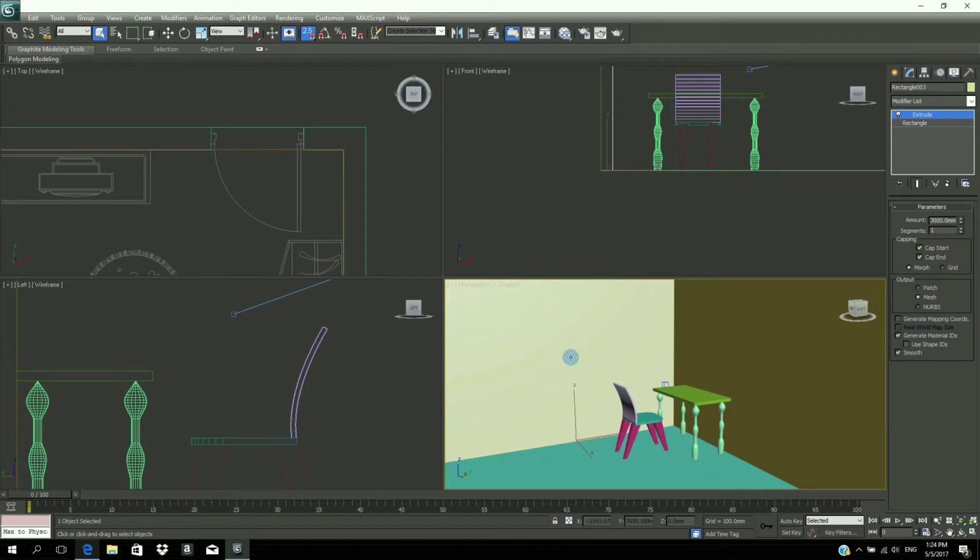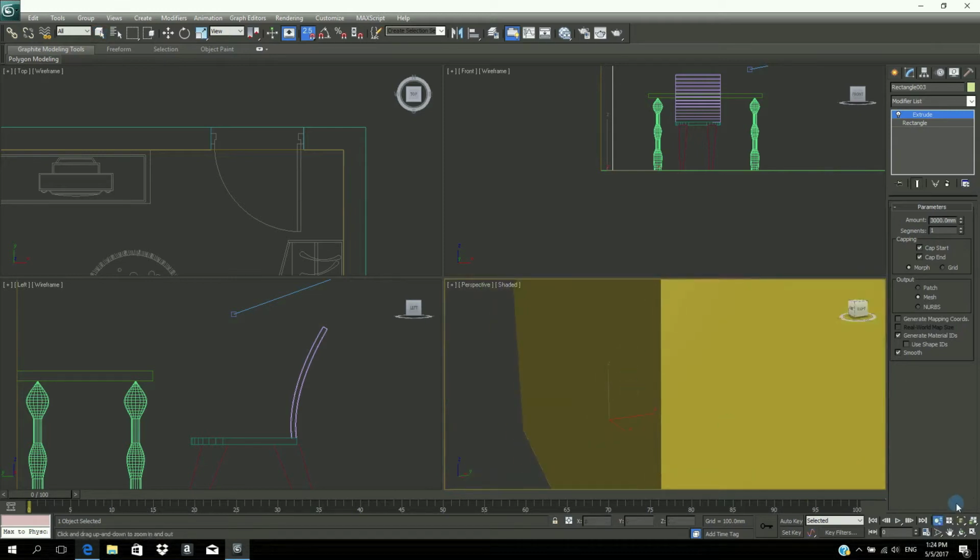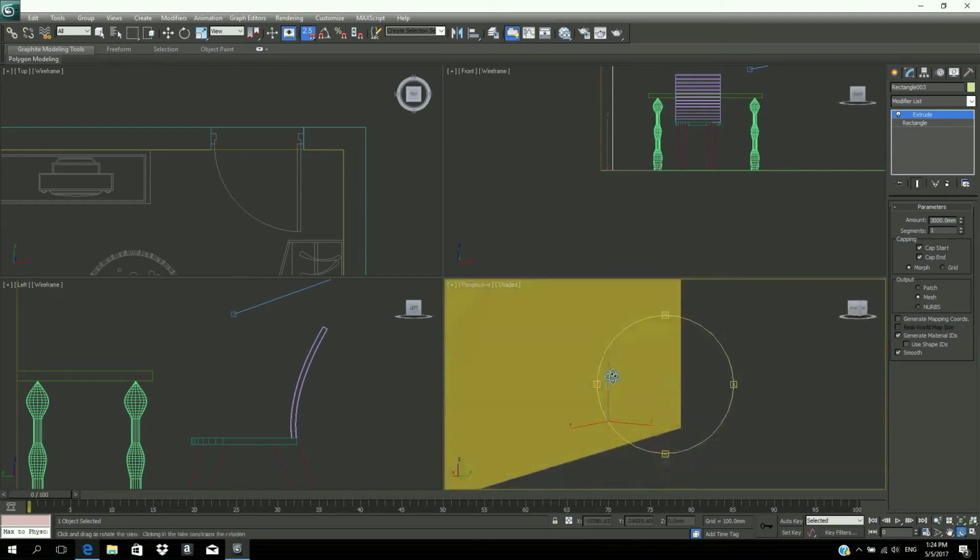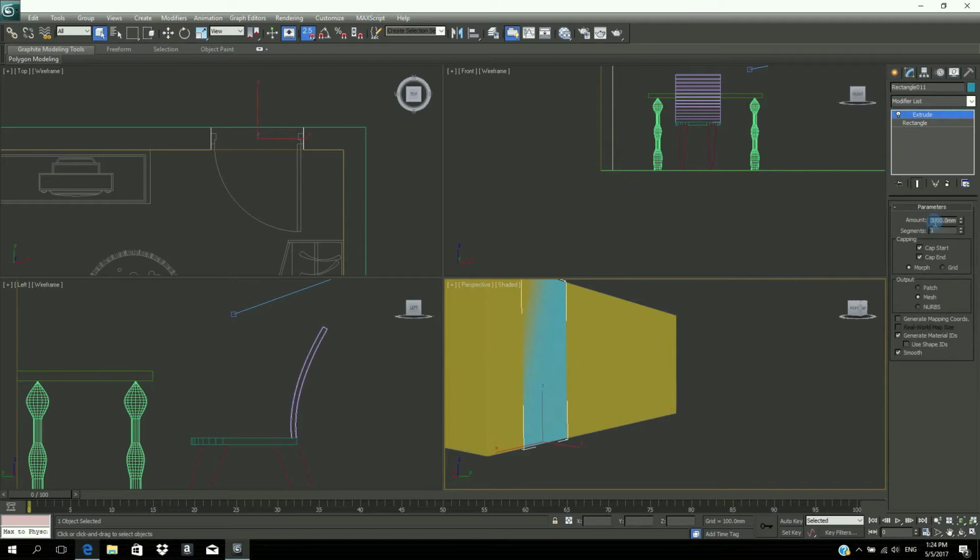The reason why we went to perspective is because we want to zoom out and zoom in of this space, and we don't want our camera to get adjusted according to that. We just want to zoom out to create the hole. If you do that while you're still on camera, then you'll notice the camera in the top viewport will start moving around. That's why we converted it to perspective, because now we're going to zoom out and use the orbit in the lower interface bar. And we're going to try to see the spot where we created the door.